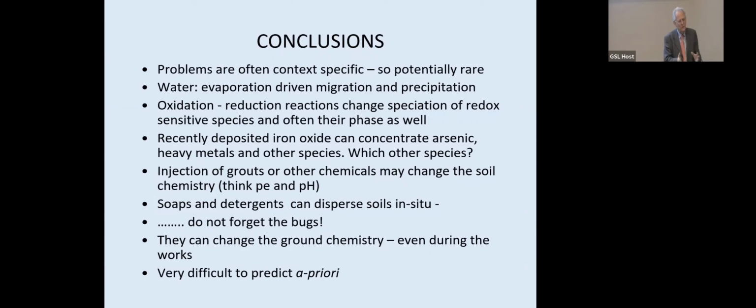So if you've got a niche environment where it wasn't particularly acid, you could get hydrogen sulfide, then you dissolve the lining, and you get that same process happening underneath slimes on dewatering pumps if they get covered in sulfide. So it was basically, in some ways, stainless steel was not the right material underground because its resistance to acid requires oxygen. And I gather it's rusty there.